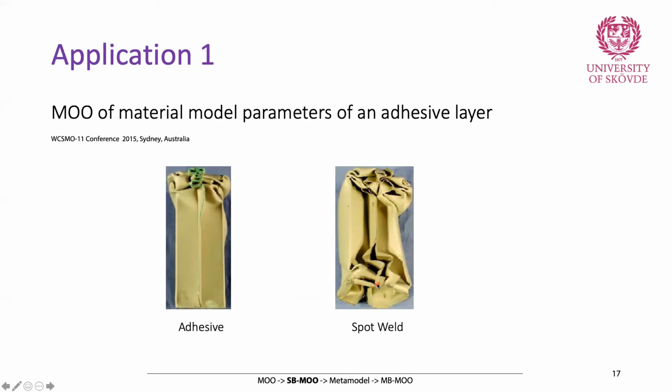So adhesive has a lot of benefits over the traditional joining methods. Other benefits are the galvanic insulation property of adhesives, the vibration damping of adhesives, and also the sealing capacity. But in order to use adhesive in joining materials, we have to be able to simulate the joining methods. And for doing that, we need finite element method.